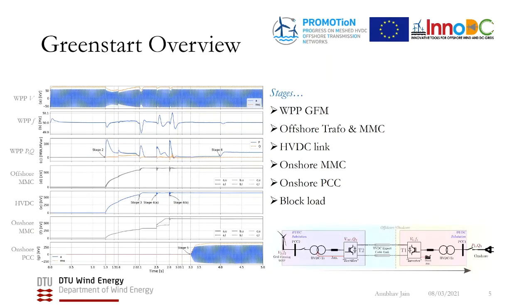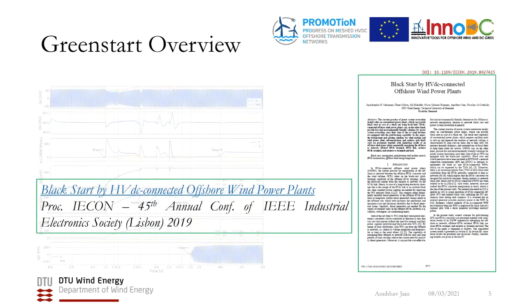Some assumptions were used for this preliminary study. The average model of a grid-forming wind turbine was used, in that no transformer inrush, saturation and switching details were implemented. Also, simultaneous energization of wind turbines inside the wind power plant was done. This means synchronization was assumed. These assumptions have been removed in the upcoming studies of EMT transients in detail, with the focus area narrowed down later on. This work began during the promotion project and resulted in a paper presented at IECON in 2019.